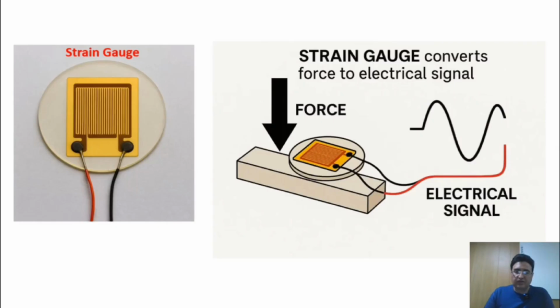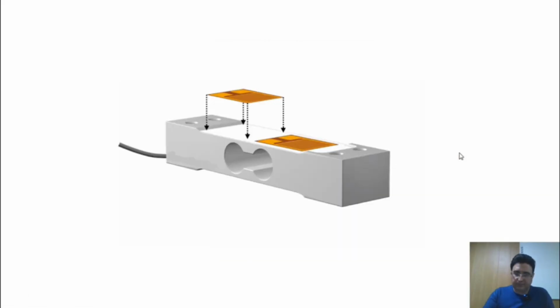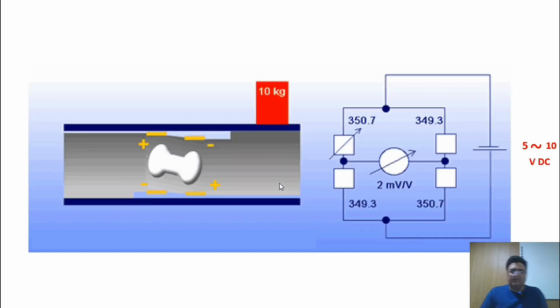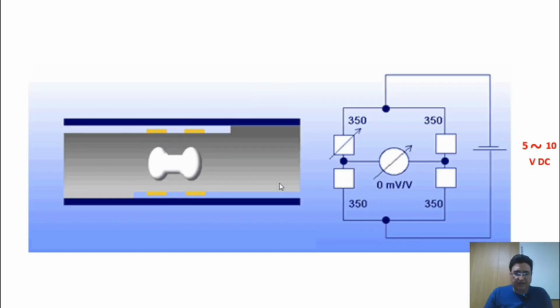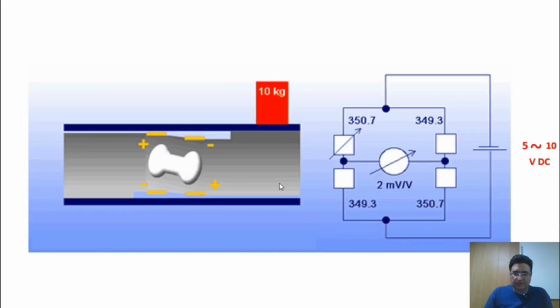So, if we connect our load cell to a display and apply force to the load cell, we can see the weight value on the display. We can observe it. Now, this particular image clearly shows us how the strain gauge is precisely positioned on this robust metal core. Alright, here we can get thoroughly familiar with how a load cell fundamentally works.